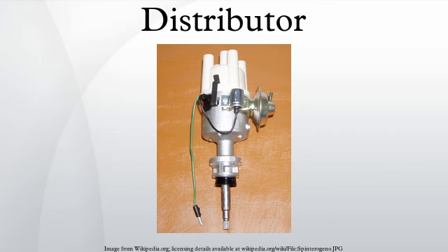In traditional remote distributorless systems, the coils are mounted together in a transformer oil-filled coil pack, or separate coils for each cylinder, which are secured in a specified place in the engine compartment with wires to the spark plugs, similar to a distributor setup. General Motors, Ford, Chrysler, Hyundai, Subaru, Volkswagen and Toyota are among the automobile manufacturers known to have used coil packs. Coil packs by Delco for use with General Motors engines allow removal of the individual coils in case one should fail, but in most other remote distributorless coil pack setups, if a coil were to fail, replacement of the whole pack would be required to fix the problem.